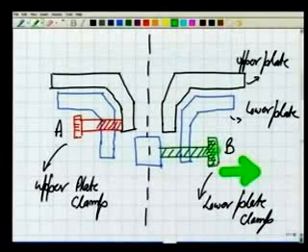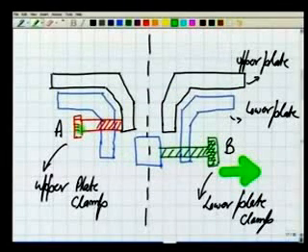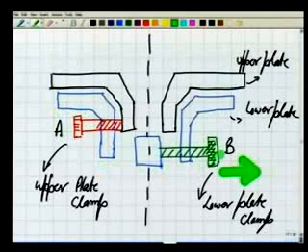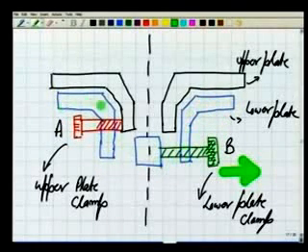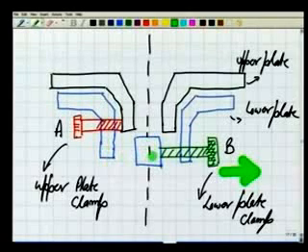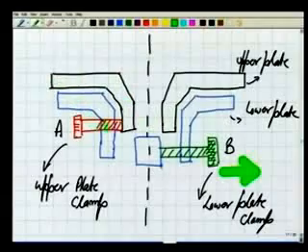So I have clamped this B and unclamped A, so this lower plate is clamped with this spindle, while this upper plate is free to rotate because we have taken this A towards this side. So in rotating the instrument, only the upper plate will rotate.